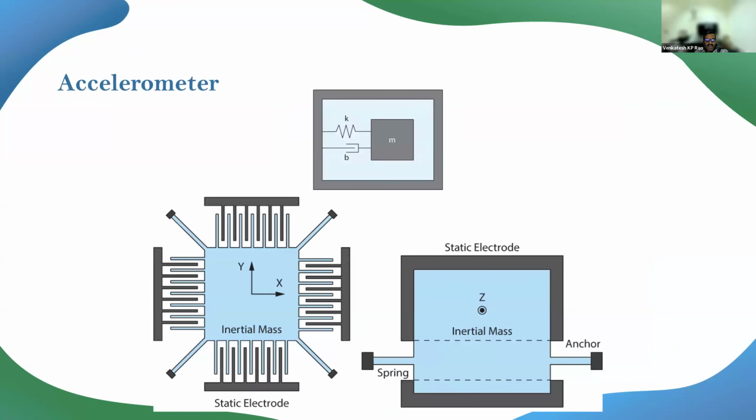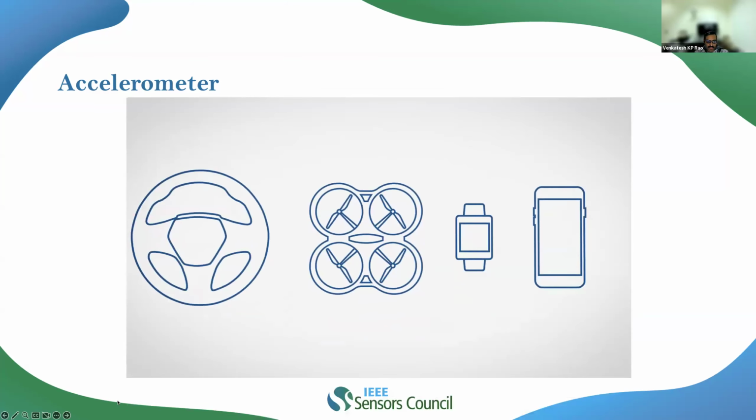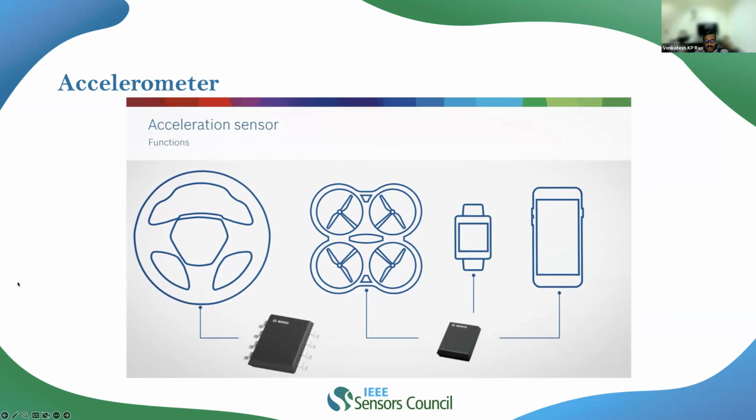On the other hand, in an accelerometer, we have the proof mass suspended with the help of a set of beams, and whenever there is an input acceleration coming onto this, what happens? It leads to the deflection of the proof mass, which will lead to what? The change in capacitance between the comb fingers under consideration, right? So that's how it's sensing the acceleration. So look at the working principle of the accelerometer and the process behind it.